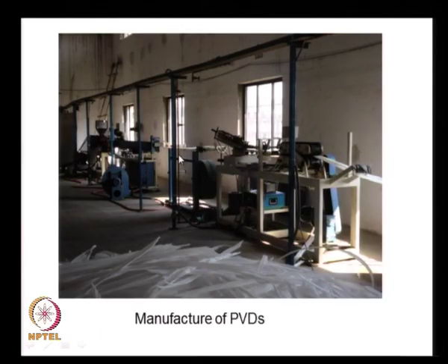And here we see a picture of the PVD being manufactured. These are all the plastic cores that are put inside the PVD, and they are all joined together by a welding process, by heat bonding, and then these plastic cores are covered with a geotextile. In this particular case, it is a woven geotextile.